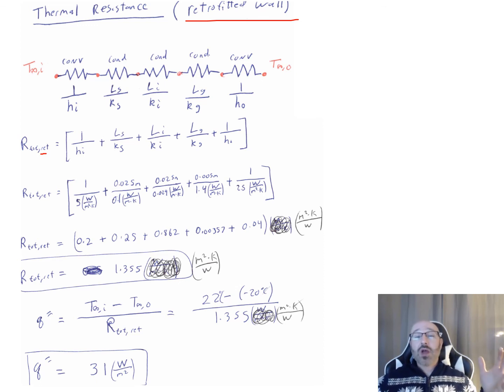So this is one where I would suggest you go back to the original diagram that you just drew, draw out your circuit directly underneath it, and line up those nodes with the temperature spots on it. What we can see is we have the two air temperatures inside and outside. So we have convection on the inside and the outside of those two surfaces. And then we have conduction through the 3 layers. You have your sheathing, your insulation, and your glass. SIG: sheathing, insulation, glass.